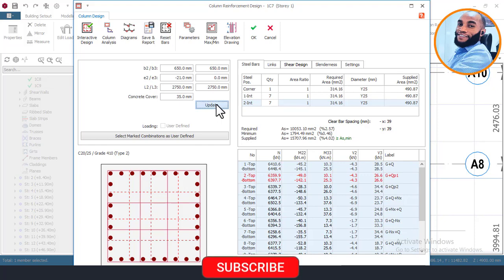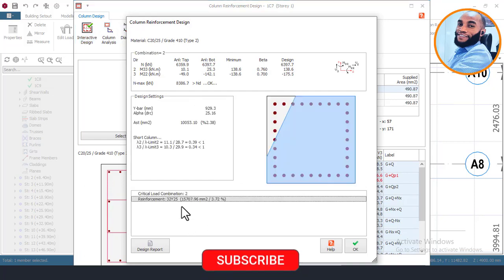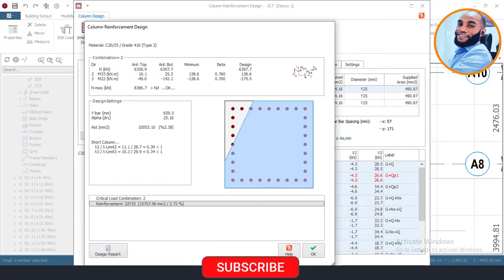So I'll come here right now and then say okay, and then we set bars and then we design again. We'll have 28 number of bars. They're about 32. Okay, 32 is 32. So that means that the load coming on that column... Oh, yeah, that's true, because in this area that column is where we have that swimming pool. Okay, that's fine. So that's why we're having that. So this is okay. 32 number of Y25 is okay.